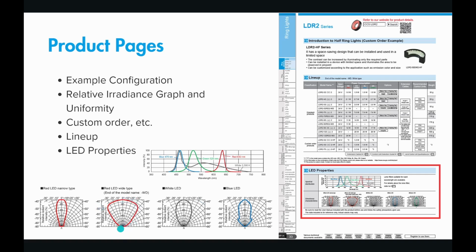So you can see here, if the light is facing on a table and shining straight up, we put a meter measuring the irradiance of the light. When the meter is perpendicular to the light, that's where we're at our brightest point, or 100% of the light's intensity. And as we angle the meter around the light, is probably a better way to say it, as we get to 20, 30, 40 degrees of an angle, our relative irradiance drops down.